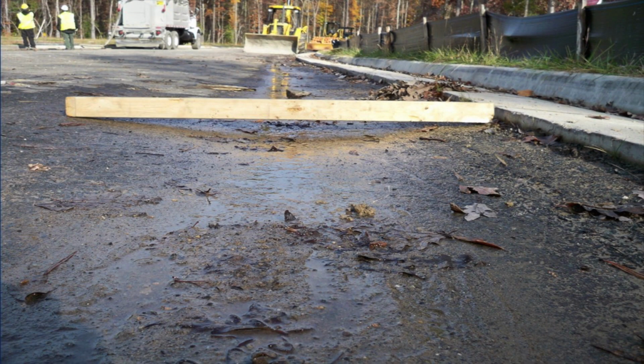Some of the issues that we run into too, we have a lot of trenching issues where we have new utilities. Utilities have been installed some time ago, and now you have that sagging, if you will, and it reflects back through the asphalt. This particular case, this is another new subdivision. They haven't even put the last layer of asphalt on top. And you can see where you're already losing some of the sections of road because it wasn't compacted properly. The reclamation process will allow a bridge over that section of roadway.